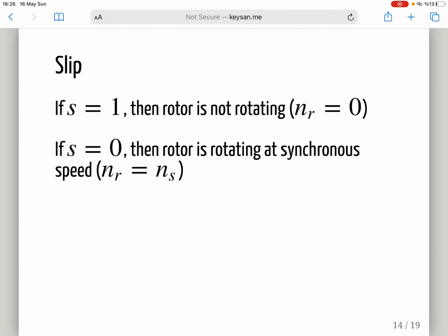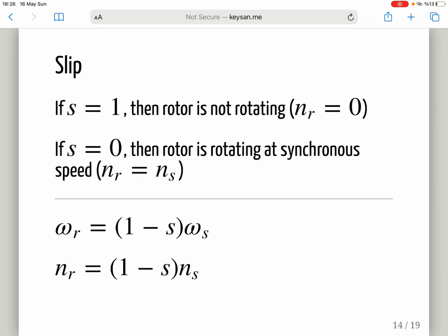You are rotating the magnet, but the aluminum disc is rotating at exactly the same speed as that magnet. So from the aluminum's perspective, the magnets are not moving, so it is as if it's not creating any varying magnetic field. That is really important. So the induction motors cannot work at synchronous speed. We will see that in a couple of examples.